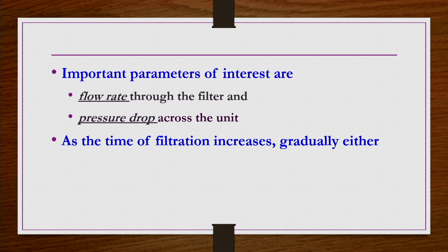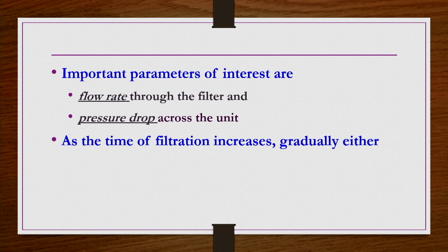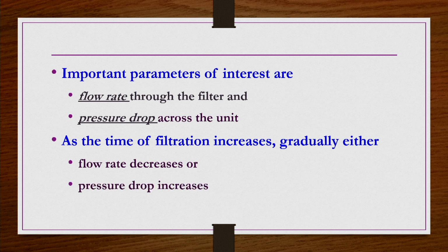Accordingly, the volumetric flow rate of the filtrate that we collect from the other side of the filter medium decreases, or the pressure increases in order to maintain the flow rate of the filtrate. So, one of the two cases happens: either the flow rate decreases or the pressure drop increases.